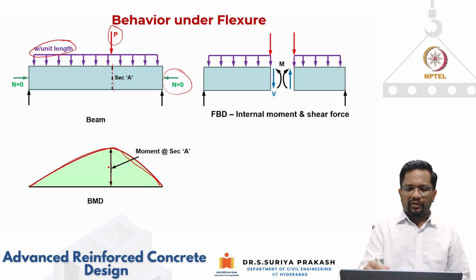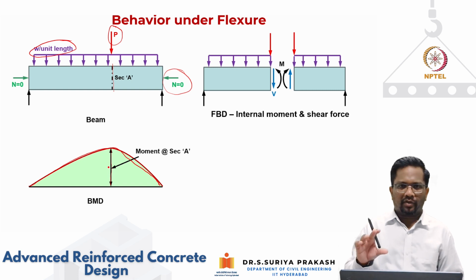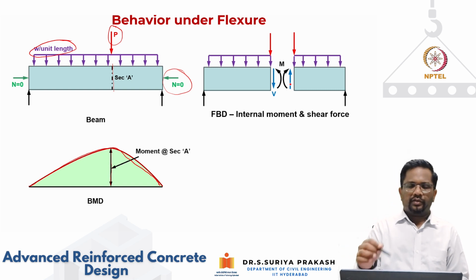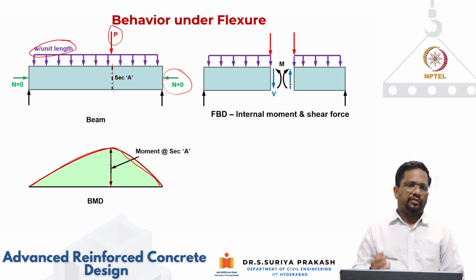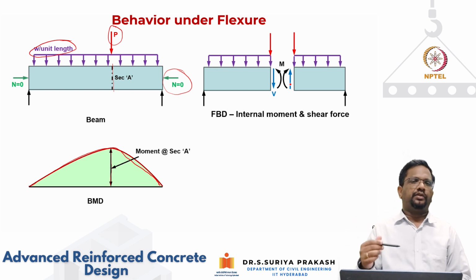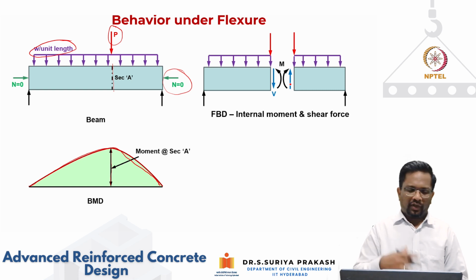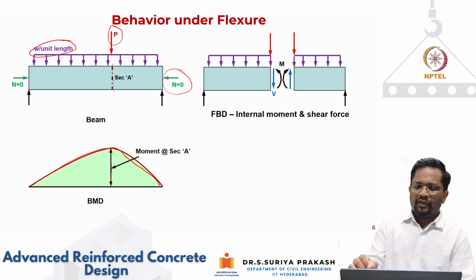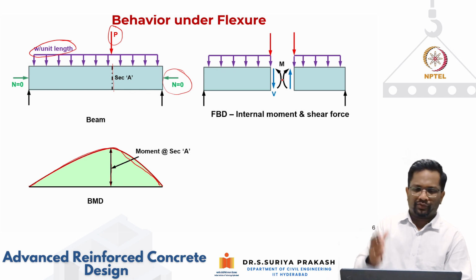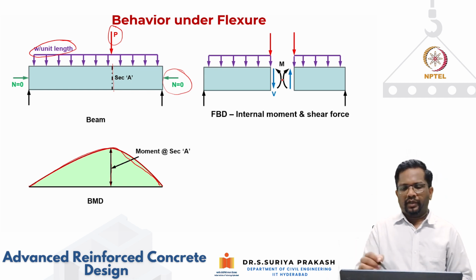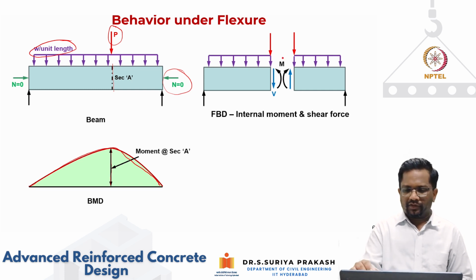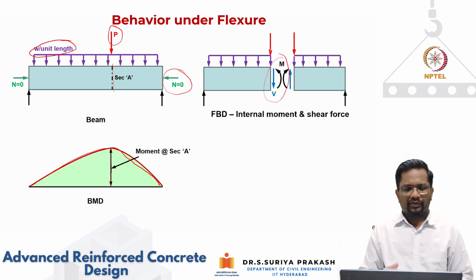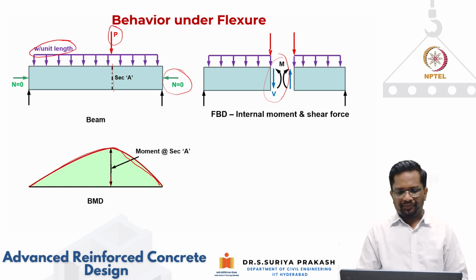If you look at it again, draw the free body diagram from your basic engineering mechanics course. Once you cut a section, and you look at the left side part of the beam and the right side part of the beam, to keep the two parts in equilibrium, you need to have some internal forces. Those are the internal forces that we are going to use for designing your reinforced concrete section. So for example, you see here the shear force and bending moment you expose once you cut, right? So these are internal forces. This is what we are going to use for design. You know that from your structural analysis.